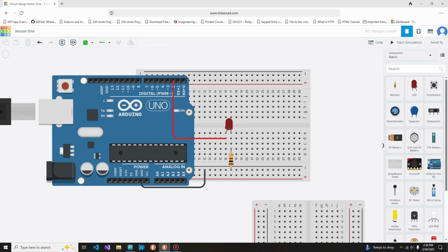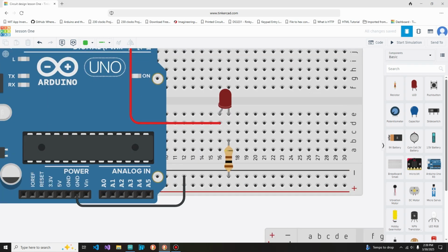Moving on with that. So we're going to connect the pin 2 to the anode side of the LED. Remember, these work like I have it set up from top to bottom because we have it on the side now, but it'll connect to the anode. Now the cathode side, we're going to connect a resistor to this. Now resistors, glorious little things.